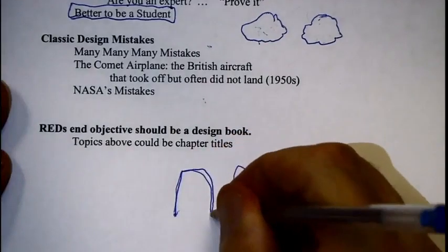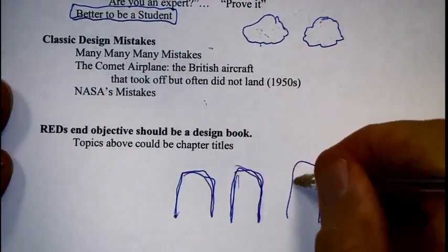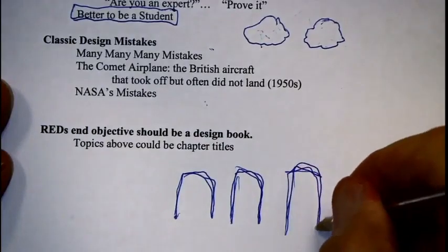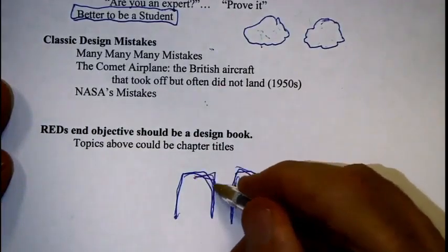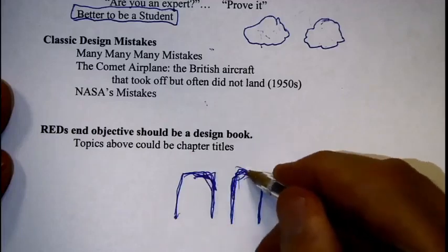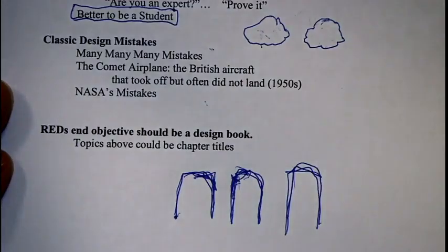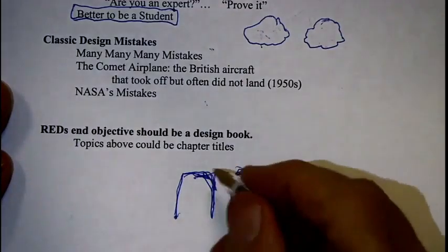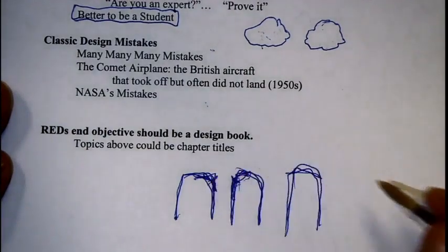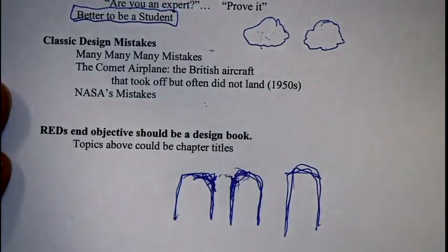That's absurd. How do windows crash an airplane? Well, the problem with this is that these windows were a bit too squared. And what would happen is the stresses would concentrate right at that corner, and the crack would form between the two.